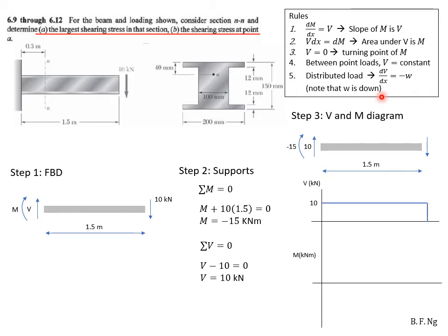First of all, over at this end itself, because it is attached to a wall, moments and shear are non-zero. Shear itself will start at 10 because over here V equals 10 at this fixed end, and it will be a straight line all the way to the end before you go back down to 0.